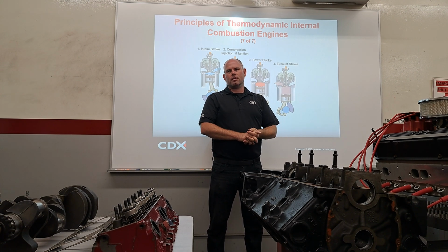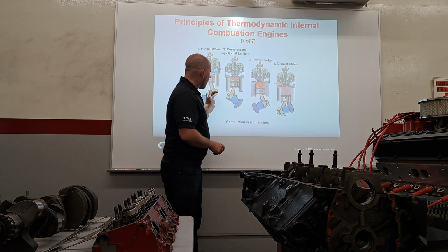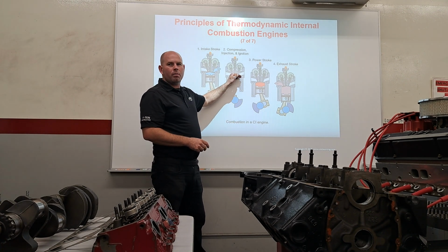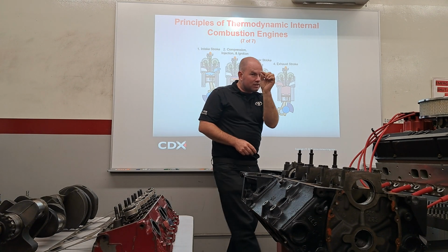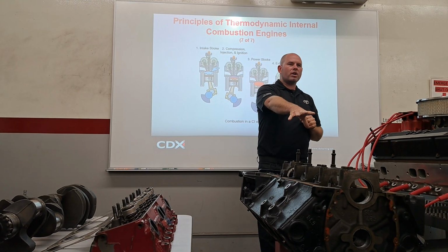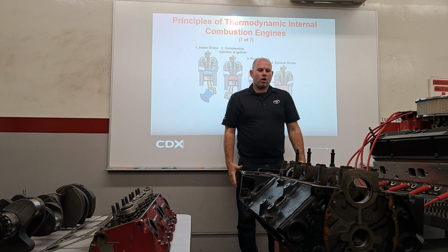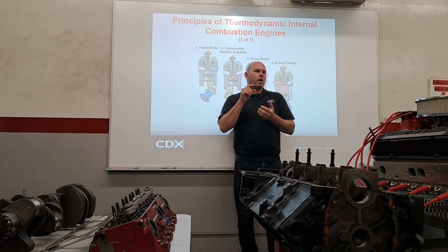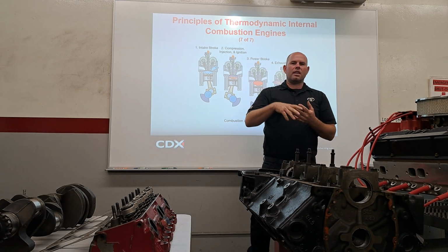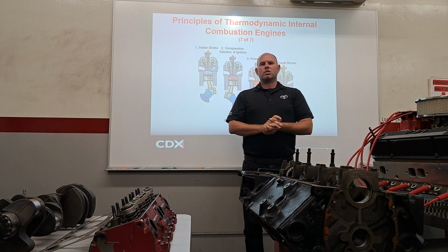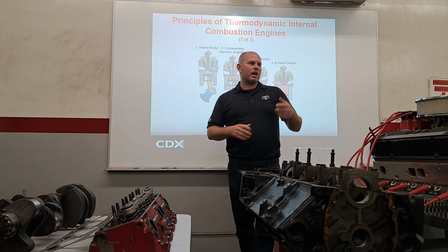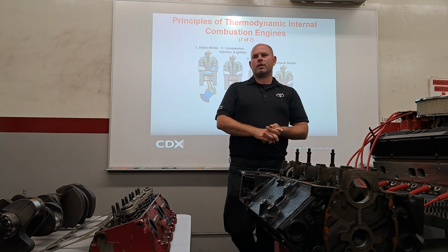In a diesel, on compression, when it gets to the top, we time at what exact precise point we spray the diesel. So we have air compressed, and then at the right moment, we spray the diesel, and that's already so hot that that's going to start the combustion, right? So a diesel is going to have really high compression, like 20 to 1, something really strong.